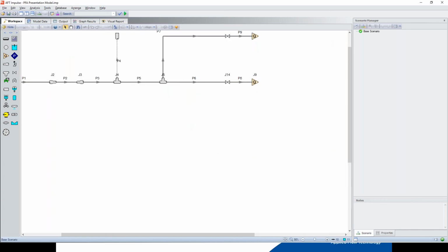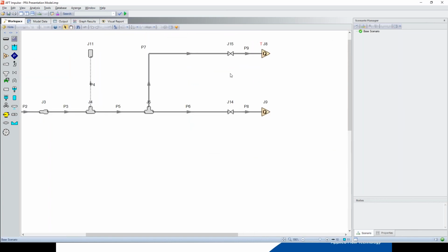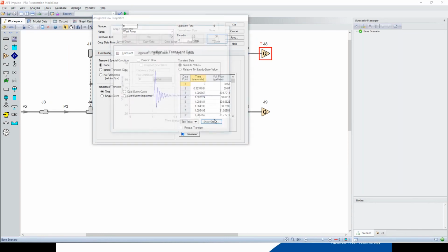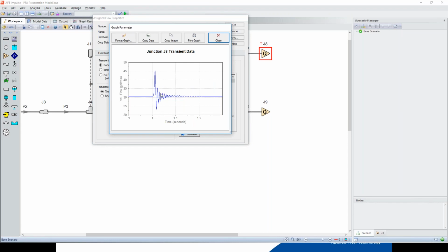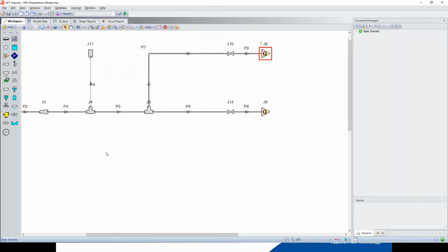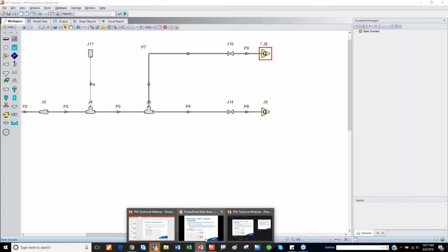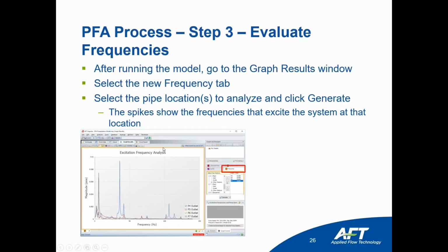And finally, we unselect those pipes that we don't want to be included in the system. As we said, pipe 2 is a bottle, so it's not really a pipe. Also, pipe 8 and pipe 9 are bottles, so we don't want to include them in the analysis. And pipe 10 is isolated acoustically by the centrifugal pump, so we also want to exclude it.